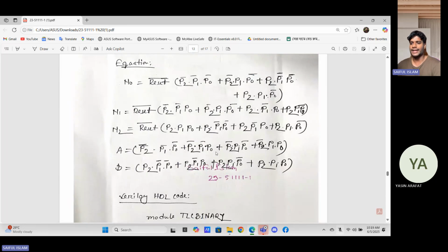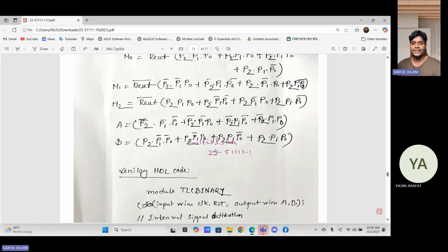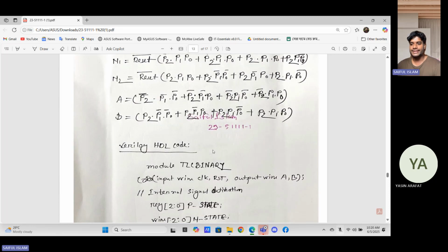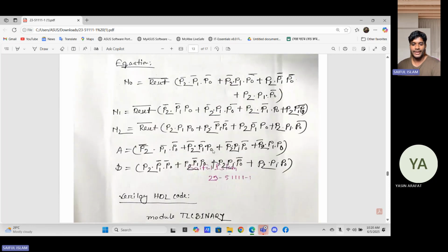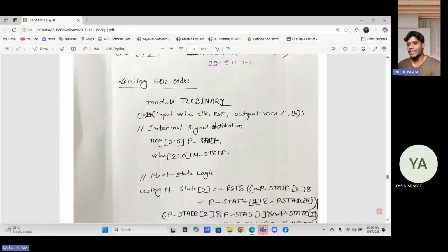To implement the FSM, I wrote the Verilog code with a state register and counter. The next state is determined based on whether the counter has reached value TH and TL, switching between state A and state B. The output is simply assigned A when in state A and B when in state B. The counter resets on every state transition, ensuring the processing time matches the output period.